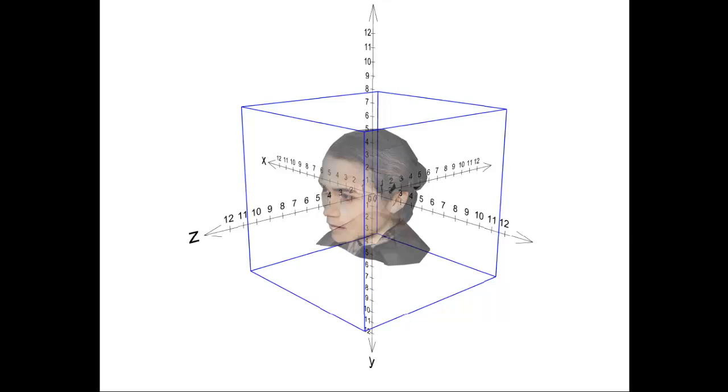suddenly we can look at this person and see that plane of projection coming to the front, coming to the side, and this is what we refer to as an orthographic projection. We could trace this person out on all 6 sides of the orthographic projection, and if we unfold that box so that everything lines up, the top view would show the person.